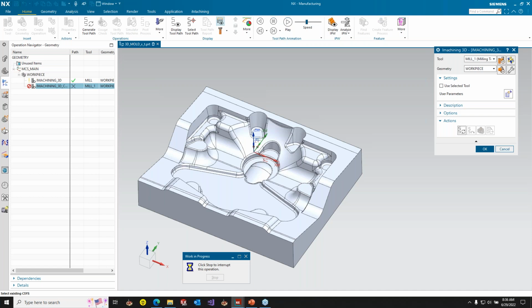Let's see, what are some of the other things we've done in the background of iMachining 3D? The adaptive engagement angle for the step up was a pretty big thing that we did. In the past, at the deepest depth of cut, you were cutting with like a 30-degree engagement angle. We basically kept 30 degrees through the entire toolpath, so your step over was the same the entire toolpath.